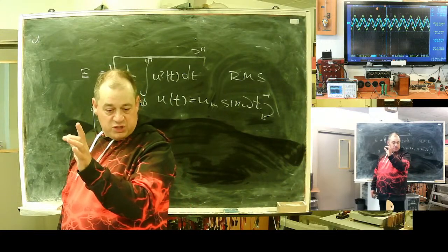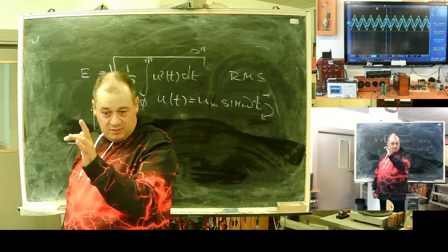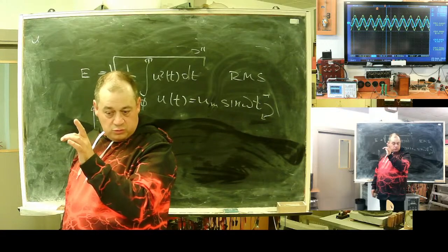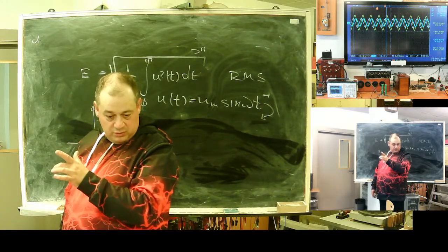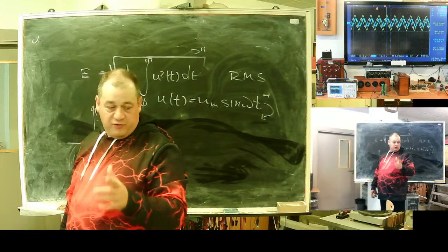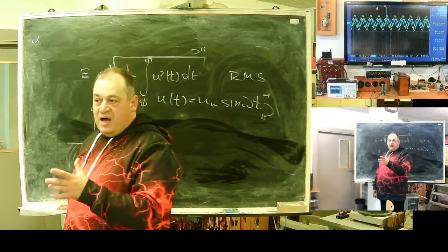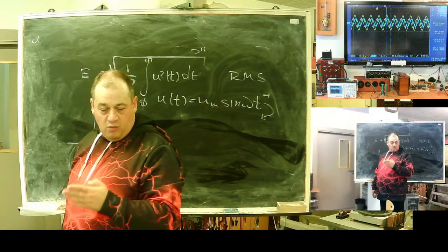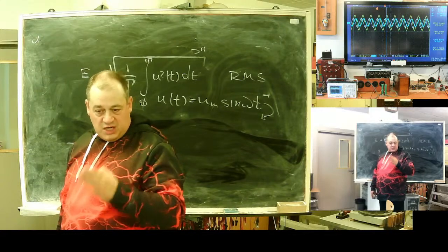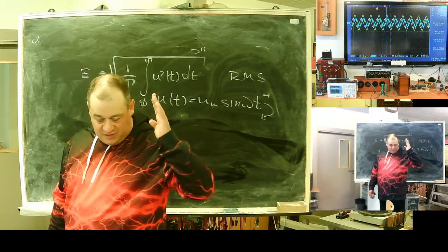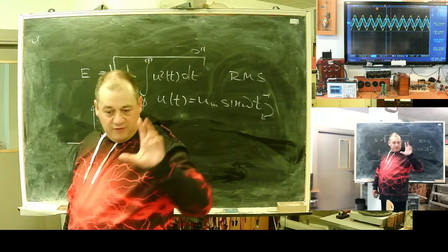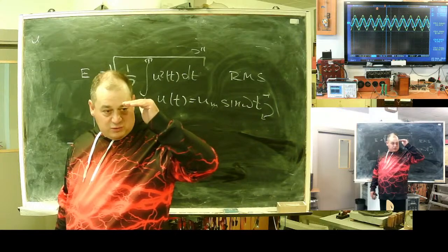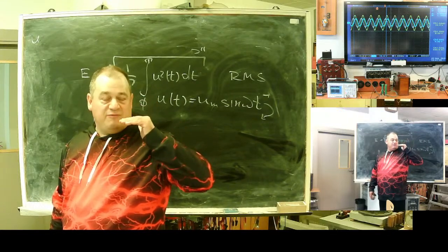Power will be a multiplication of current and voltage in some form, yeah? This square root of 2 is needed to get the power the same. We know power from DC. For AC power, we should always divide by 2, or just keep everything clear, assuming that vectors are not amplitude, but amplitude divided by square root of 2, to be an effective value.